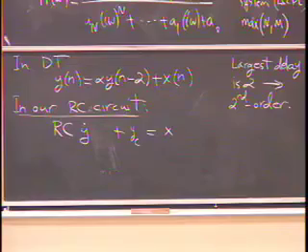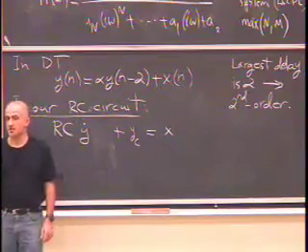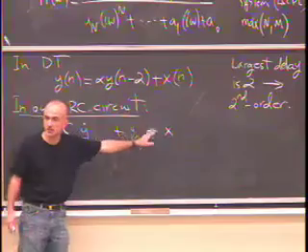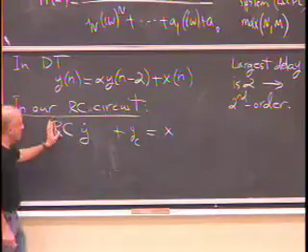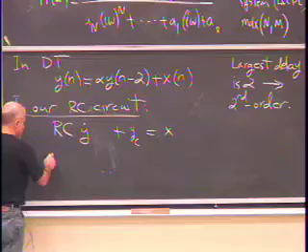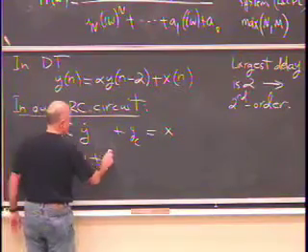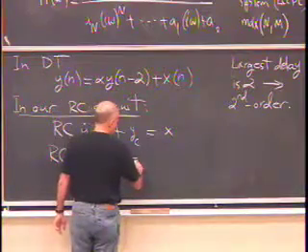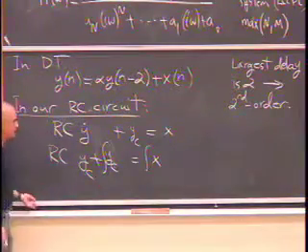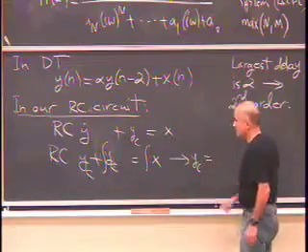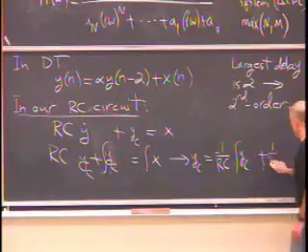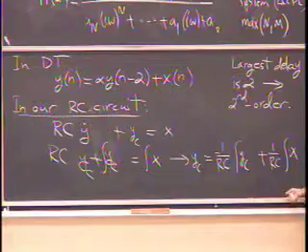In continuous time, the memory elements are things like capacitors, anything that has an integrative feature. And the way we find that is you integrate symbolically. You don't actually carry out an integration. You integrate symbolically both sides. How many times do I have to integrate so that I no longer have a derivative? Once. So I have RC y plus integral y equals integral x. And so what this says is y is minus 1 over RC integral y plus 1 over RC integral x.